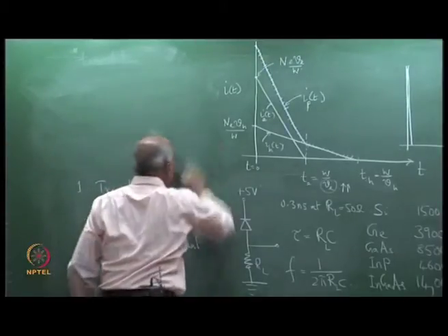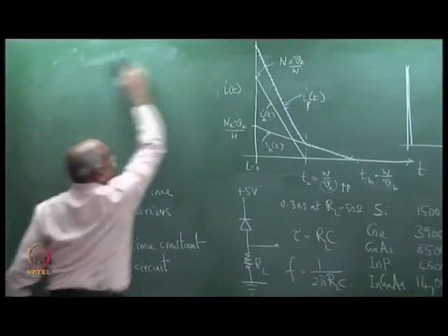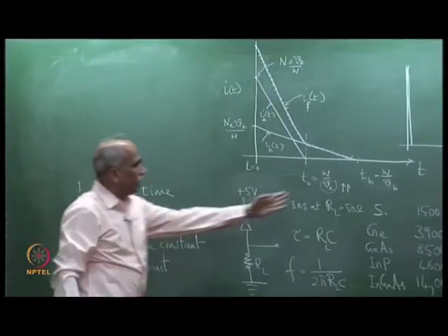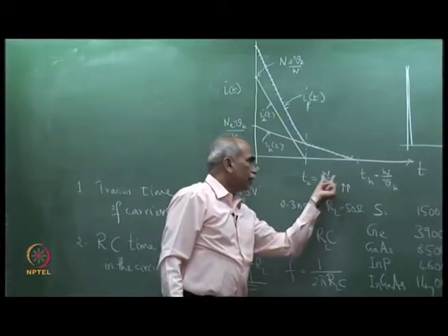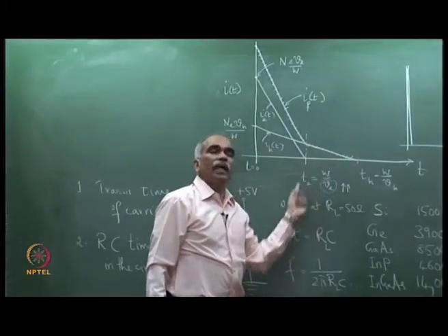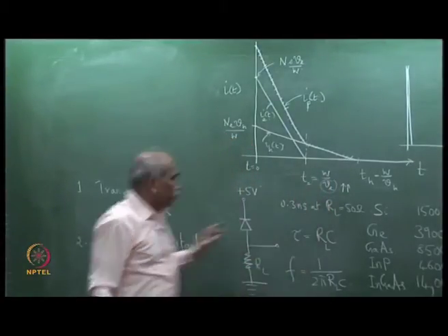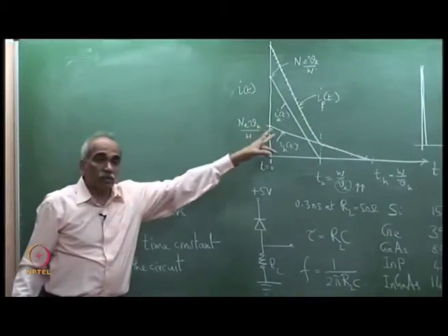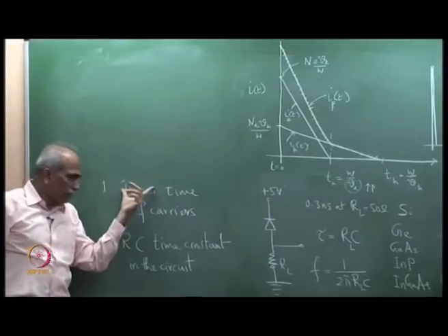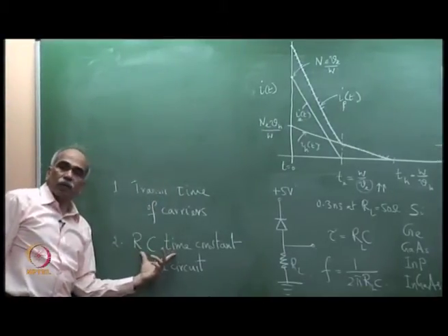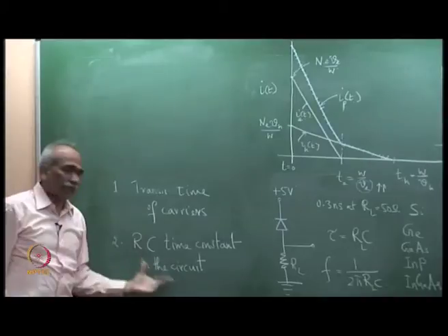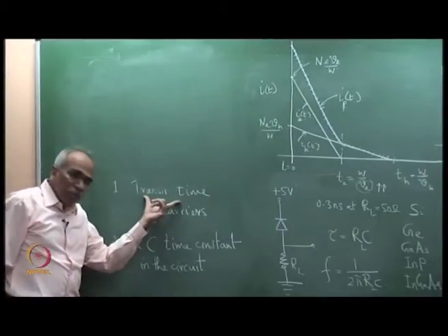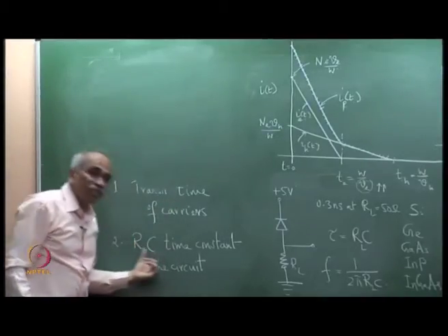We have some time. If you take Ve very large and very small W, Te can be very small, and therefore the impulse response, determined by two factors, transit time and RC time constant in the actual system circuit, can be minimized so that it is primarily determined by this.